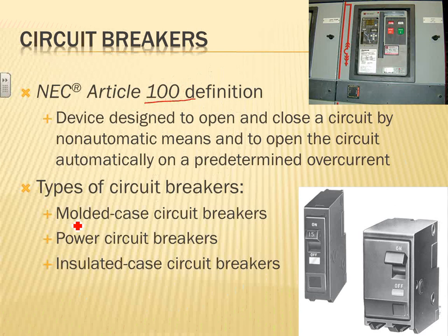It will automatically trip under a predetermined overcurrent condition. So if you have an overcurrent condition, higher current than what the equipment is rated for, it will trip inversely proportional to the time. Okay, a couple of things, guys, about circuit breakers, and you are very familiar with them. Looking right here at the top, this is a power circuit breaker, the top-notch power draw-out circuit breaker. It makes sense to use it at 1,000 amp or higher.